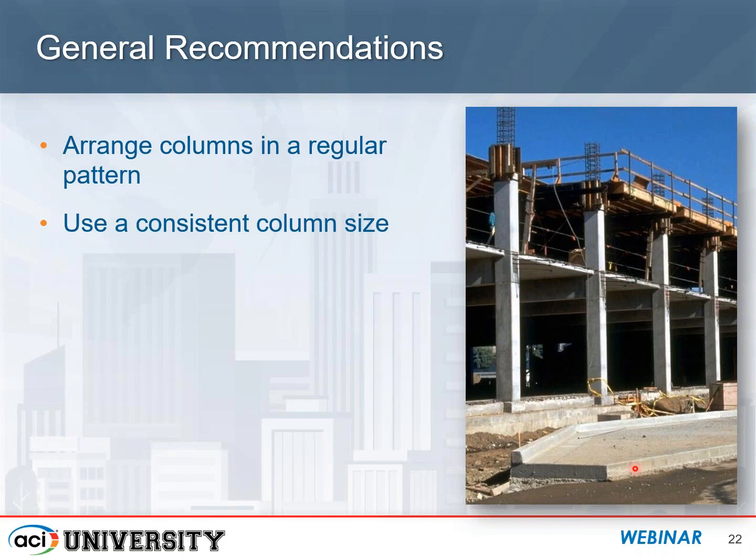Now, even if you can't have a regular pattern based on the architectural requirements, having a consistent column size will help in a very similar fashion. So it's this ripple effect it has through the structure that just leads to savings in time and cost.